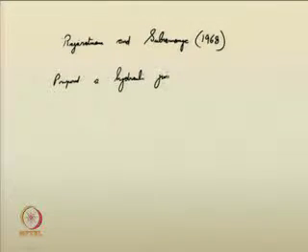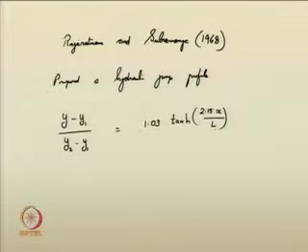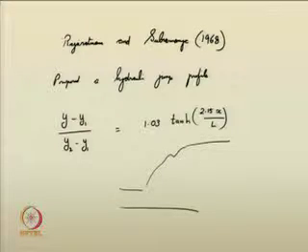Using a large experimental data, they proposed a hydraulic jump profile as such, that is (y minus y 1) by (y 2 minus y 1) is equal to 1.03 tanh(2.15 x by L). With this also they proposed the quantities. This is your depth y 1, this is your depth y 2.